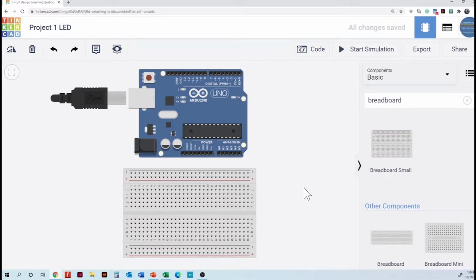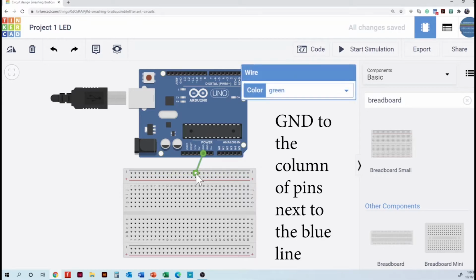As soon as we have the two components, the next one is going to be the power to our breadboard. It's important to know that this breadboard has two rails, one negative or blue, which means ground, is represented in Arduino by GND, and it has another rail in red, which is positive, and that means 5 volts. So those are going to be the connections. They are connected horizontally. So if you connect ground in any of the pins that are horizontally, they are going to be all connected to ground.